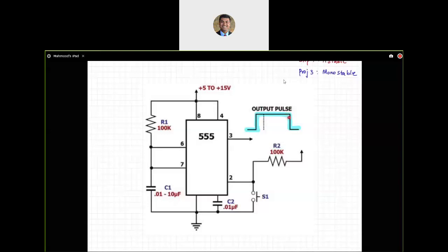But as you notice, this is not going on forever. This is just one clean pulse and done. And you have a switch that is getting debounced. Where is that switch? The switch is connected to pin number 2 there, indicated as S1. So that's a bouncy switch. And the output over here on pin 3 indicates the same switching behavior of S1, however, it is the debounced output. So that's the goal. And we are using 555 timer over here.